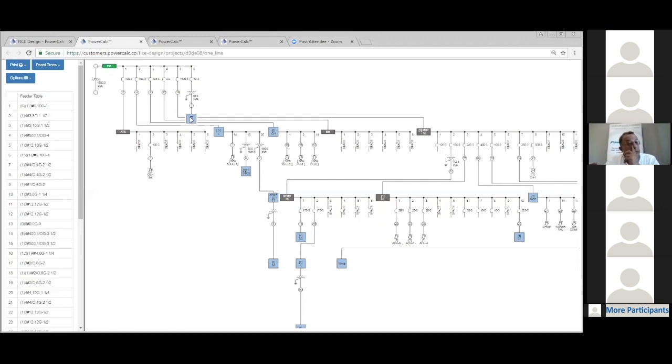So it's very important that we run the fault current calculations, and that will be the worst condition if it happens, and that energy has to pass through the circuit breaker or through the panel. It has to be able to interrupt it and isolate that particular fault without causing a lot of damage upstream or downstream from that fault, and also protect the space and, of course, the personnel in that space.